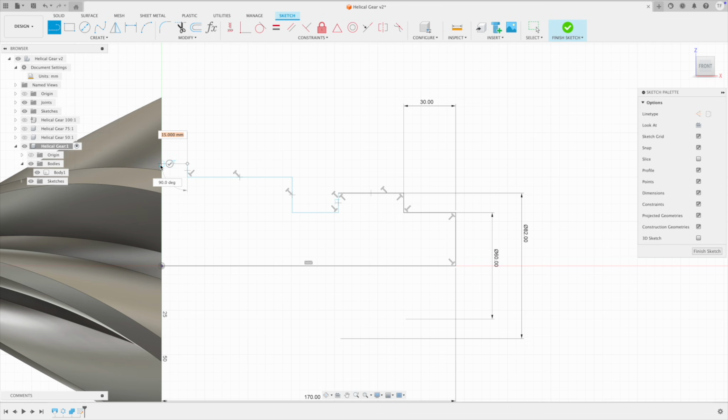There we go. So here at the very end, because we snapped this line to this point, it doesn't really snap to our gear. And the reason is because it's snapping to the grid line instead. So I want to make sure that this point is exactly vertical to this point. So how do we do it? Remember, press escape to get rid of any background tasks going on. Horizontal, vertical. I want to say that this point is vertical to that point. Very good. Now let's create a line between those two.